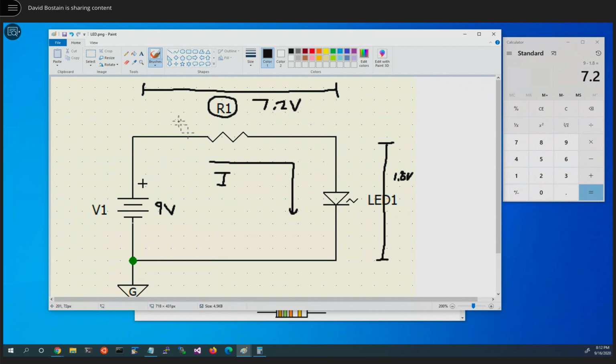That's the number we're now going to be working with in the Ohm's law portion of this part of the circuit, because resistance here and current here are relative to the voltage drop across it. Now, because we know that, and we know the current we want to be working with, because we haven't been told otherwise, we know 15 is too low, 25 is too high, 20 was just right. The 20 milliamps would be flowing here. So to get our resistor, we can take the 7.2 and divide it by 0.02. That's going to give us a 360 ohm resistor.